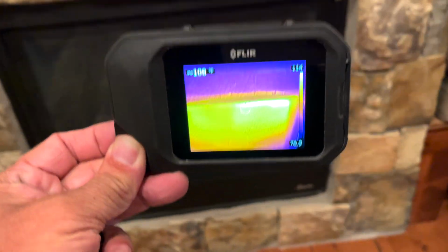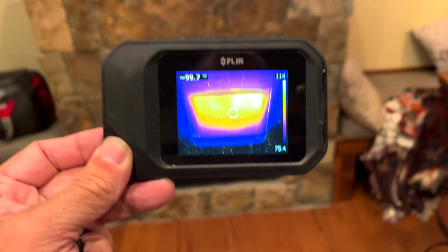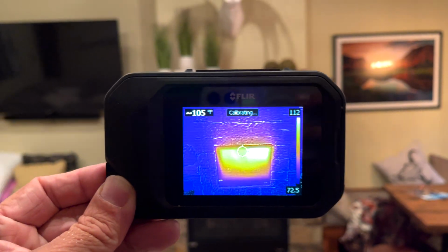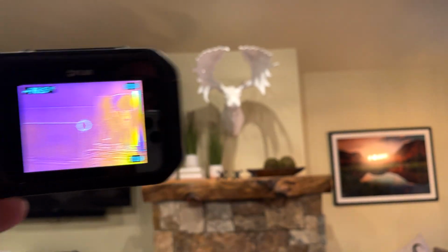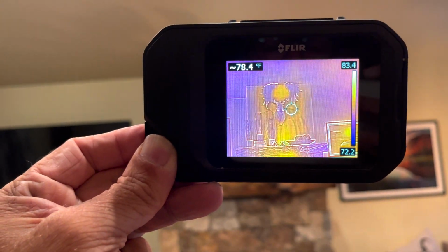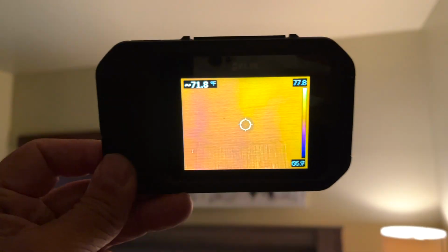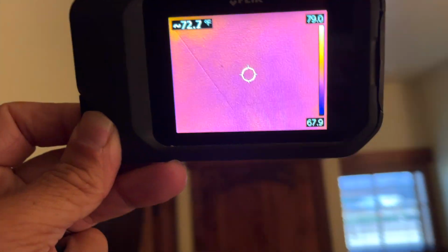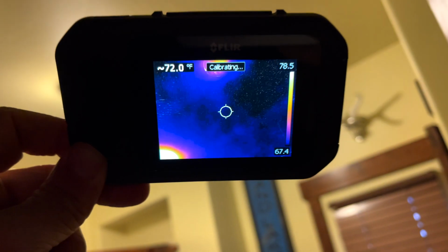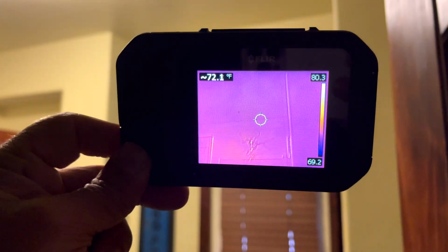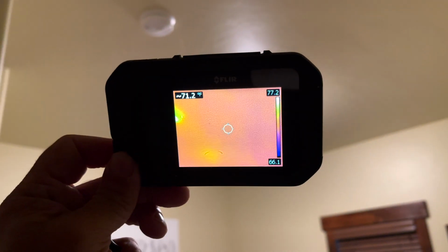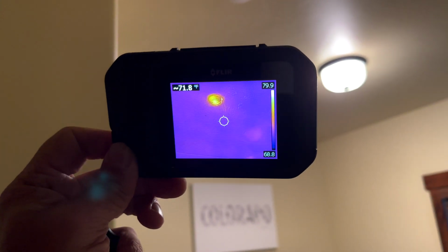So that's an inspection restriction. That'll be in my inspection report. My infrared camera helps me see things that are hot or cool. And the moose doesn't look very hot, but it's kind of cool. Looking for anomalies in the interior, the walls, the ceilings, the windows, the flooring. I don't see any water intrusion problems like we thought of when we were outside with no gutters. Light's hot, so it's a smoke detector. Interior, no anomalies. Again, looks good.